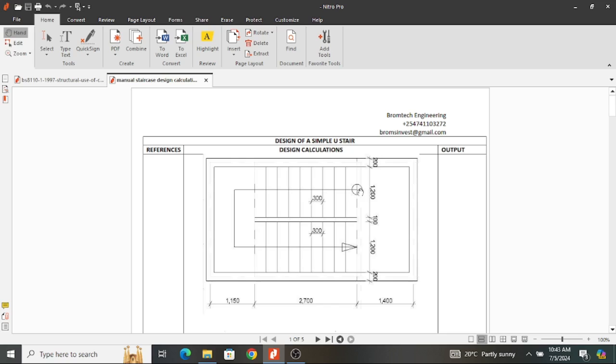But once you also study our staircase, you realize that because our flights are slanting, it is not really necessary to have the beam flat, straight, and then you slant it at this section, and then you also have it horizontal.